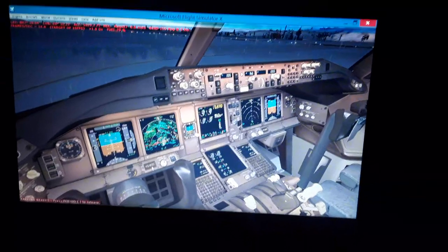knob and the heading hold switch, the vertical rate of climb and descent of the aircraft, the VS mode, or the flight path angle, the FPA mode, which determines how fast the aircraft climbs and descends in thousands of feet per minute or a trigonometric angle in degrees. And the hold switch for these modes. I'm gonna show you also the altitude select knob and the altitude hold switch. I'm gonna show you also the VOR localizer and the approach with the auto land function.